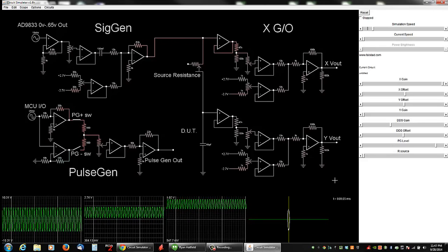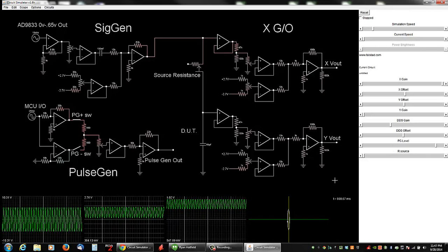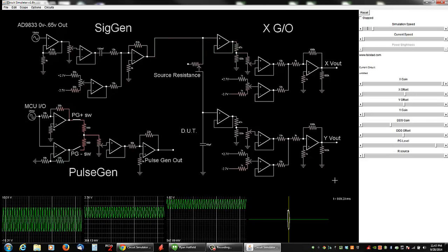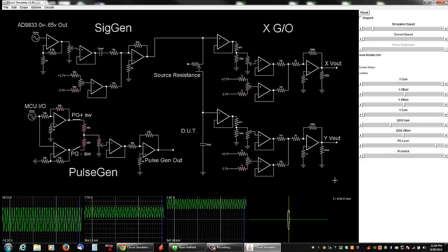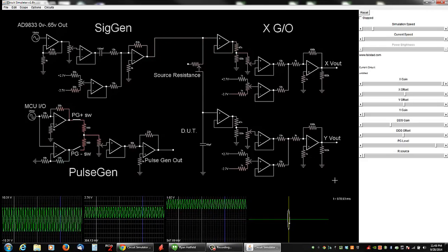Let me think. A diode in parallel with the capacitor would kind of look like a golf club. So if you know your circuit's a diode in parallel with a capacitor and you get a circle, well, your diode is open. If you got a diode in parallel with a capacitor and you got a slanted line, then you know the diode is shorted, because it's shorted across the capacitor, ain't doing any good, and your diode is conducting equally well in both directions, so the diode's not any good. I just said that, yeah. But your capacitor isn't even in the circuit because of the diode.